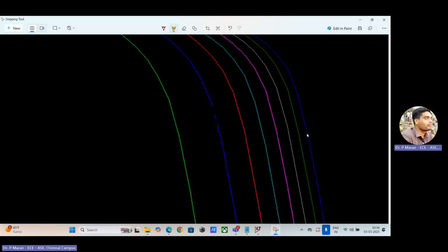In the width of the NMOS, you have to type curly braces, width of NMOS or some variable you have to define it over there. And in this dot step parameter, it should sweep 100 to 200 or 800 nanometer, whatever step you want to plot on. Just keep it, you will get the graph.